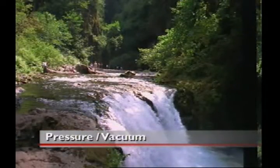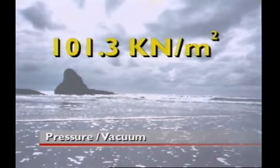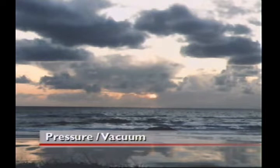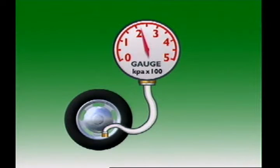Atmospheric pressure varies with altitude, but at sea level it is calculated as 101.3 kilonewtons per square metre, or 101.3 kilopascals. But if this is so, why does a pressure gauge read 0 when it is not in use? This is because the gauge indicates pressure above atmospheric pressure only. This reading is called gauge pressure.